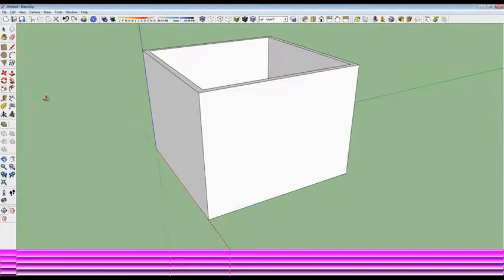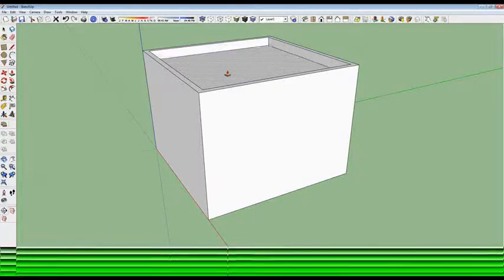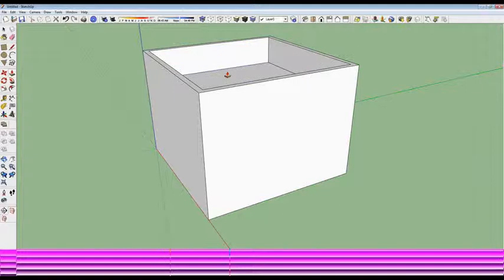Nice, encompassing Susan there. Same situation for my parapet wall, so I want a flat roof in here. I'm going to take and close in that surface, drop this down 4 feet. So I just clicked and dragged down, and it knows to go in a negative direction there as well.